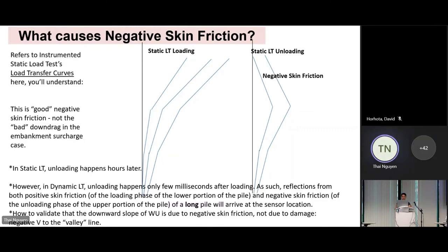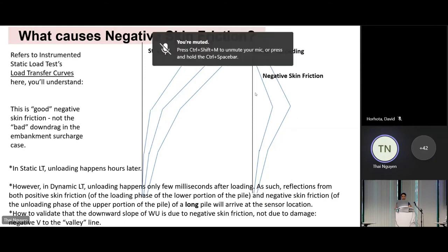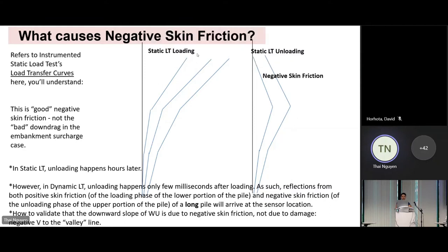Now in static load test, this unloading happened a few hours or even a few days after the loading. In dynamic load test, the unloading happened only a few milliseconds after the loading. When the hammer is still on the pile, a few milliseconds after, the unloading already happened.